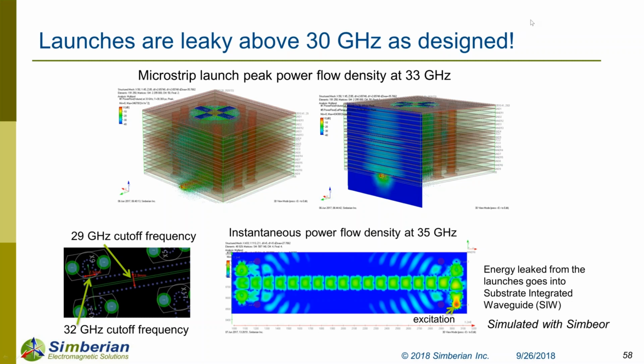And the measurements were excellent. At the end, we basically measured every single structure on the board, a few structures even far apart. You can see right here the energy escapes into the interplane area, and guess what? Things have become really coupled at frequencies above probably 40 gigahertz. So we'll see coupling between ports in completely not linked ports.